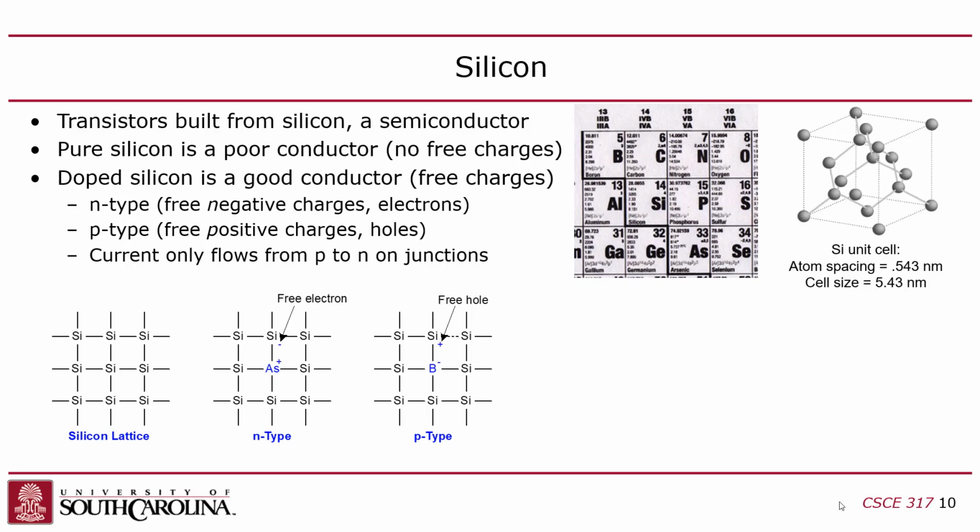And what ends up happening is called doping. Some of the dopant atoms actually replace some of the silicon atoms in the lattice, right? You can dope it more or you can dope it less. You can heavily dope, in which case you replace a lot of silicon atoms, or you can lightly dope, in which case you replace fewer.